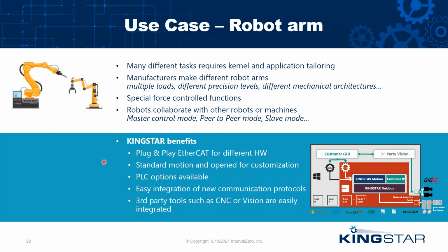The first mode is what's known as master control mode. The robot controller is the master of the whole system. Usually, you want to avoid having multiple applications and multiple controllers in one production unit, because that means more costs and more synchronization effort between the different applications.